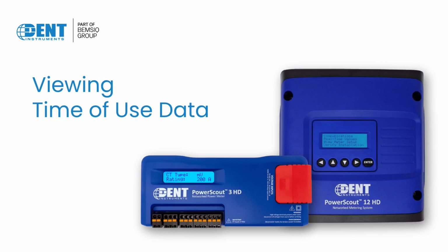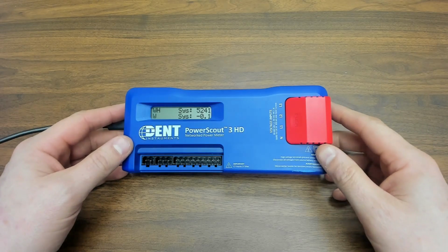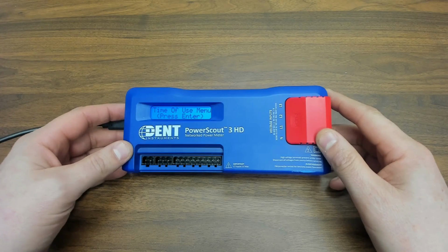Now, let's look at how to view the Time of Use data on the PowerScout 3 HD submeter. Find the thumb wheel on the side of the submeter and scroll up or down until you see the Time of Use menu option. Press the wheel to select it.